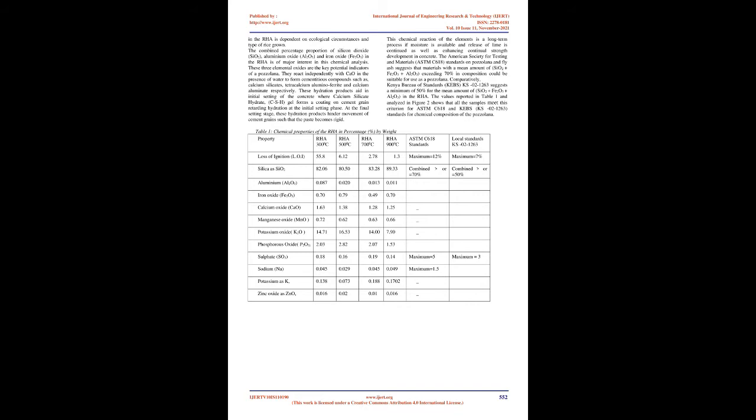3. Results and discussion. A. Physical properties of RHA. 1. Color. The rice husks burned at different temperatures gave distinct colors. Plate 2, i.e. at 300°C, black, 500°C, white-gray, 700°C, white, 900°C, white-pink. Rice husks contain carbon which is eliminated upon burning. The amount of carbon being eliminated is dependent on the firing temperature.